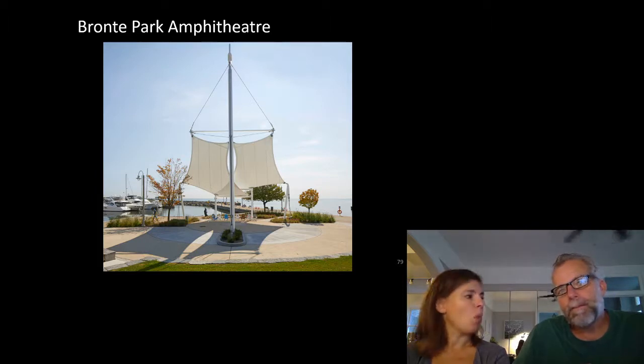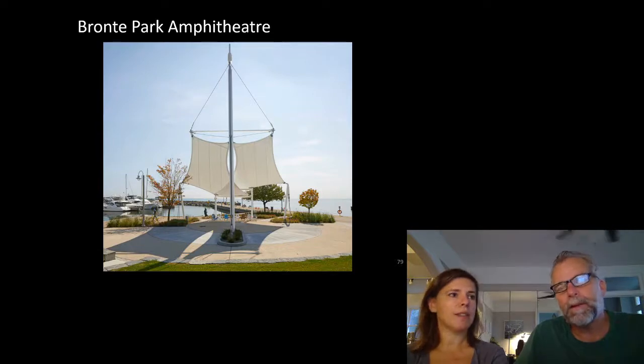It was absolutely wild. It's very quick, very lightweight compared to concrete, which is good because it was a fill site. One of the huge advantages is that all of the anchor bolts and all the lugs to receive the cables were all in exactly the right spot. Perfect. Because they were done by the steel fabricator who had to build the steel on top of it, he was able to do a fit up in his shop for elements and know exactly where things were. And you've heard me say before that the number one thing that is wrong in a project is where those anchor bolts are.